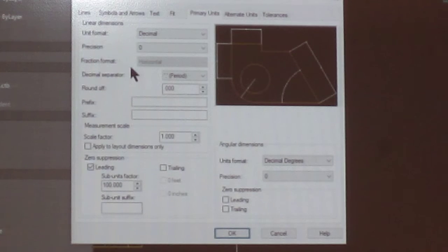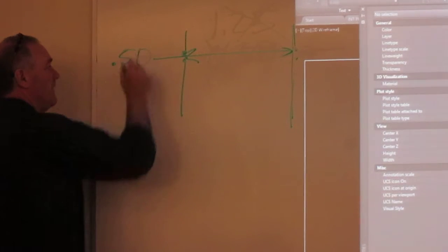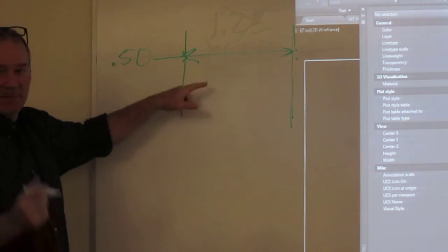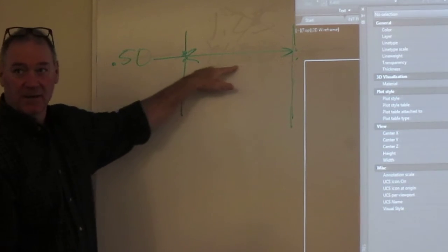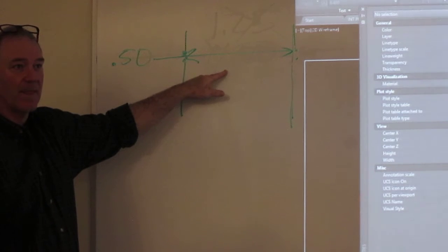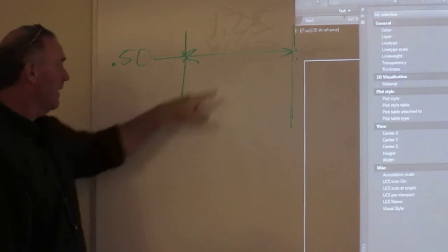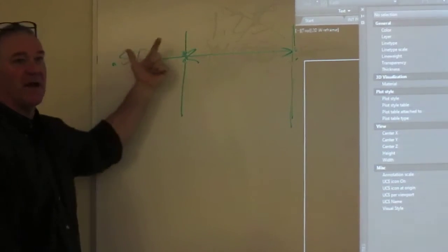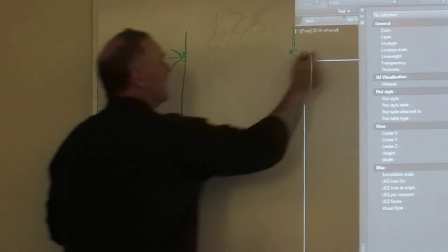Now, as it gets smaller yet, another thing I've seen on a few drawings as we get smaller, I've seen this with 0.50. Now, this will never occur. Because keep in mind, you need an 1/8 and an 1/8, an 1/8 and an 1/8. Okay? So you need 1/2 inch here. Well, this is only 3 characters. That's only 3/8. If you got room to do this, text should be in here and the arrows out. As they get smaller, the arrows should never be in here by themselves. Okay? It would be like that.